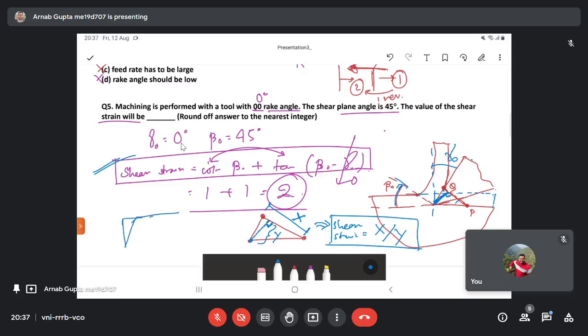This is the material after applying force about this point. This position has moved to this position. The material has moved from point P here to point Q here. Then we can say that this distance by this distance is shear strain. Same thing we have done here.